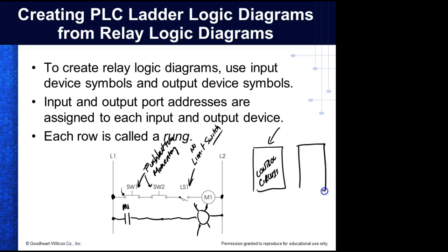And then we have a power circuit, and this is going to be high voltage. Over here we'll have a relay, maybe called M1, and then my control circuit would energize the coil from here. And over here, we might have 24 volts if it's DC.